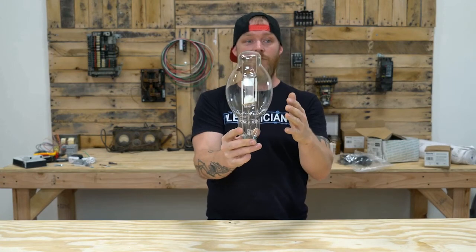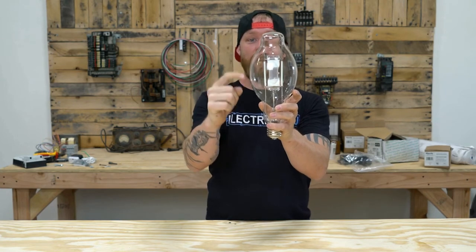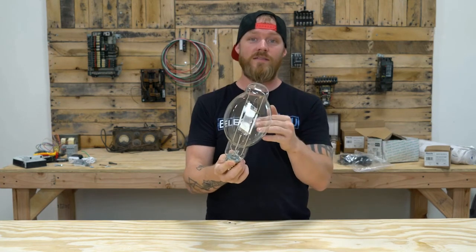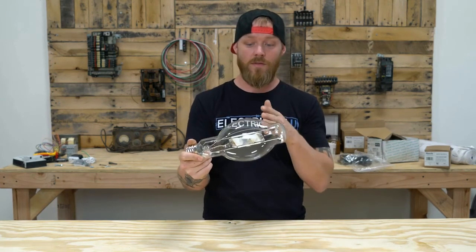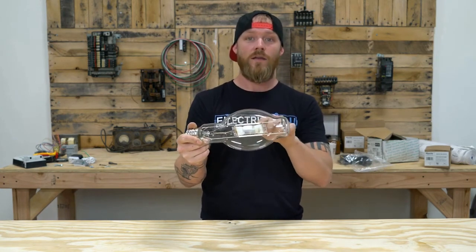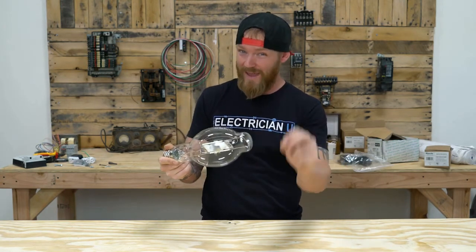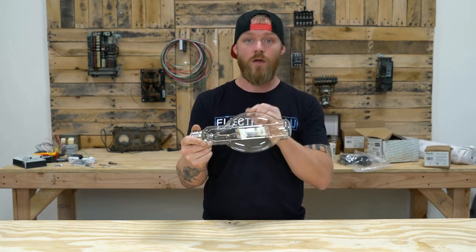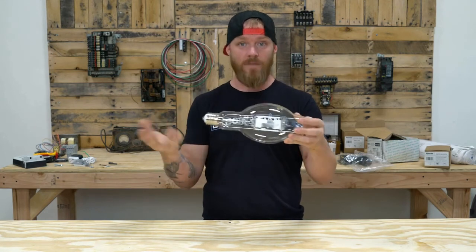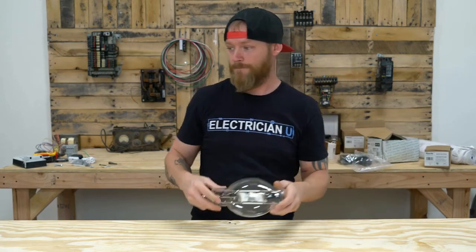It's going to look like a high pressure or a metal halide lamp, but you're not going to have the white coating that's painted on the tops of that quartz tube because it's not necessary. Remember, the only reason that white coating is there is because some of the halide salts for the metal halide light specifically have to have that coating so that it maintains the arc and those colors don't start fluctuating. So on a mercury vapor that's clear, it's just going to be a clear tube, and that's it. There's no need to have anything else. It's just mercury burning through it, and you want that blue light.